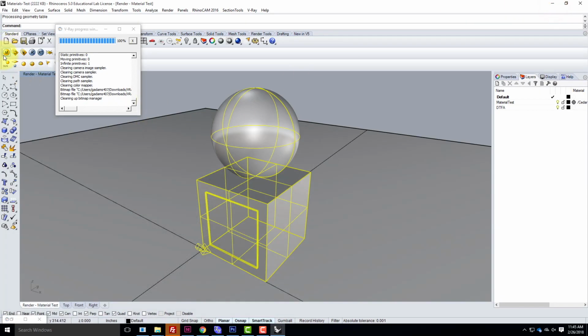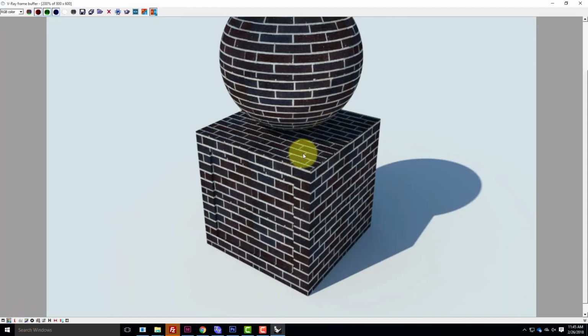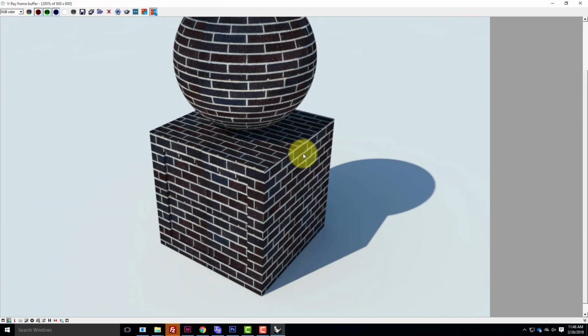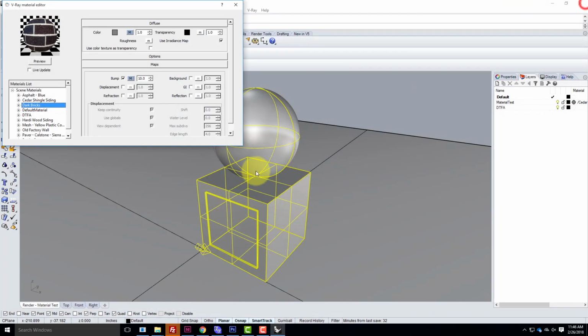When you're done with it, make sure that you pack the material. So I'll right-click on dark bricks, and I'll say Pack Material. You should also save the sample render file, this file. So you're going to save that sample render file, and you're going to pack the material. Let me try it with another example here. Let's go back to the website.